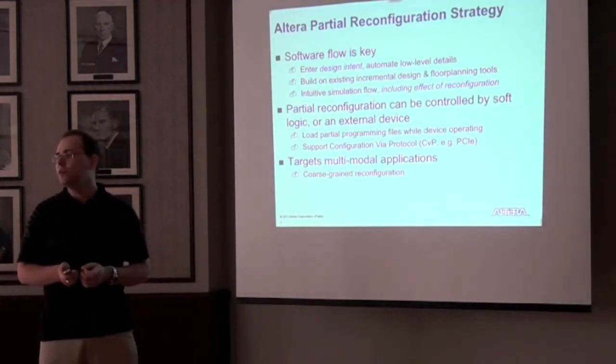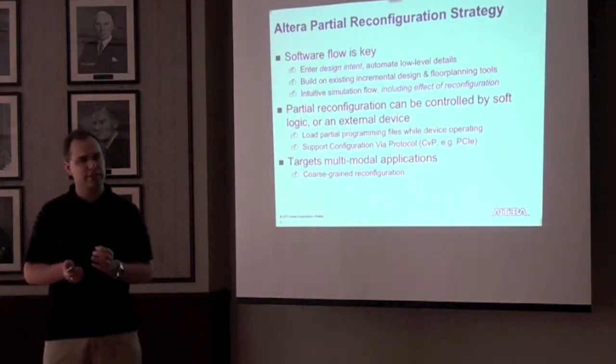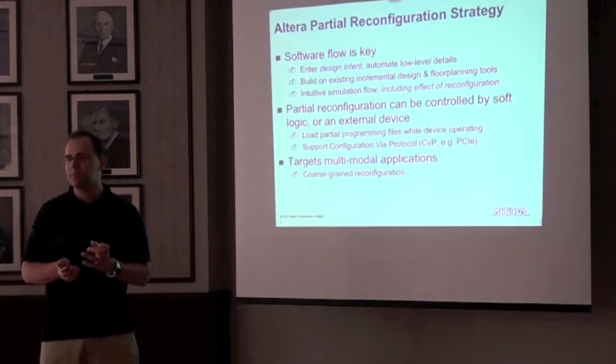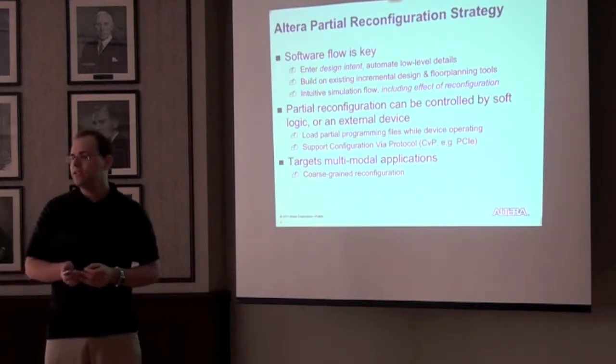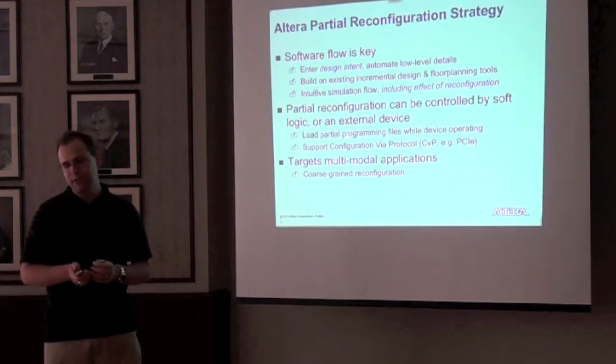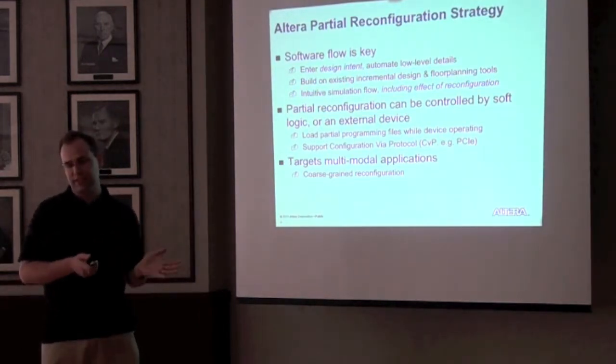And we want to provide an intuitive simulation flow, also including the effect of reconfiguration. So someone wants to be able to simulate their system before and after a partial reconfiguration event. We provide the ability to control this functionality either through soft logic inside the FPGA core, through I/O pins, or an external device such as a transceiver.